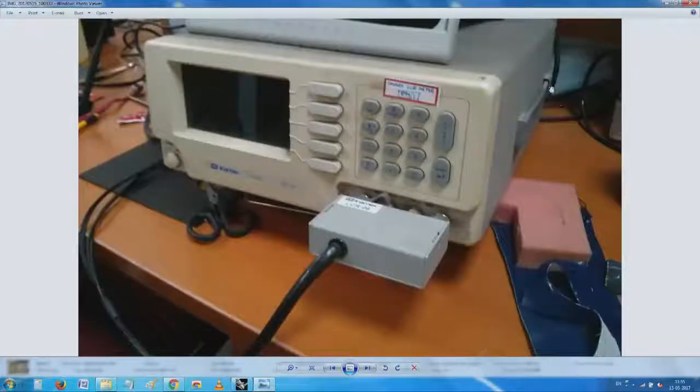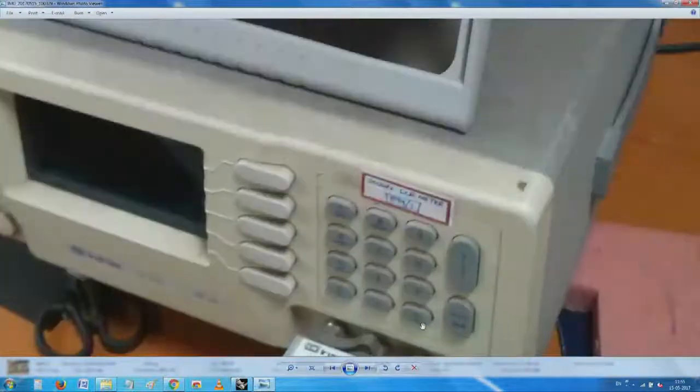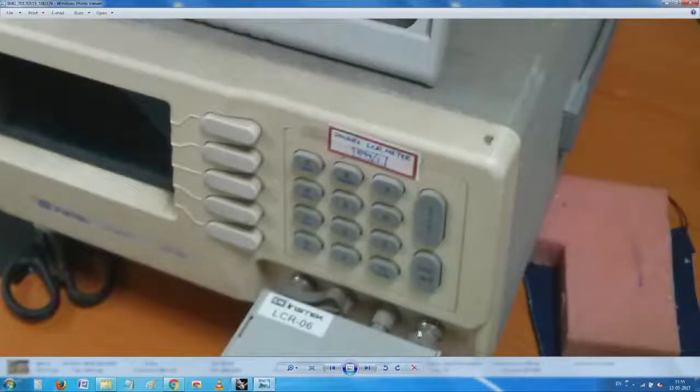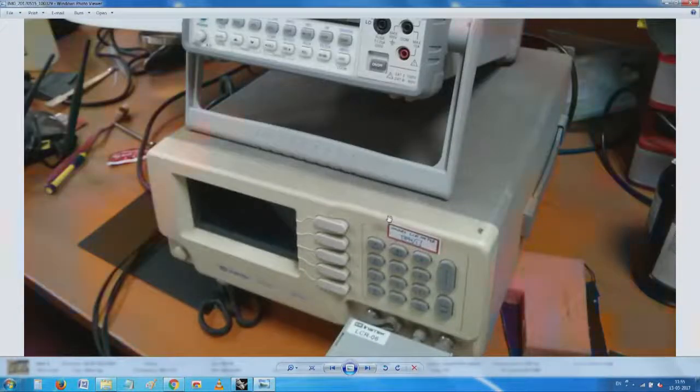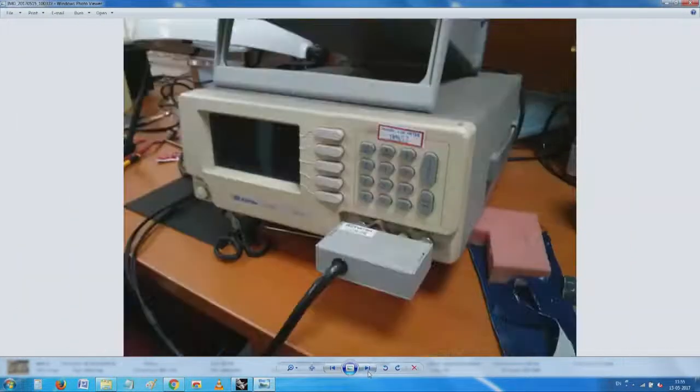So here you see a combination of it. This is probably made out of sheet metal. Then there is a handle which is made out of some flexible material. Then there is a molded cover, and then we are back again to sheet metal. In this case, probably it is inevitable because we have, see these connectors here. This looks like a BNC connector, then there are other variants of it. So these connectors require solid continuous earthing. So we have no choice but to use them.